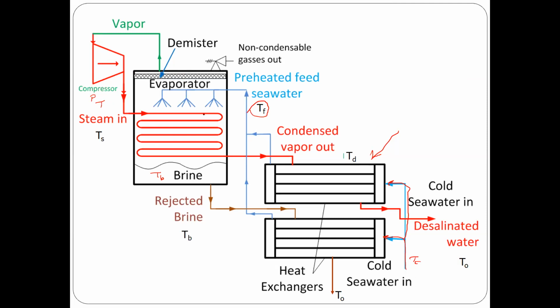This is our product. So it condenses here, and the condensate is basically going to preheat the feed, and then it will be collected as our final product here. It will go to the desalination water tank. So this is unique in that system, that you do not need any external sort of steam, but you are making your own heating steam by using this compressor.